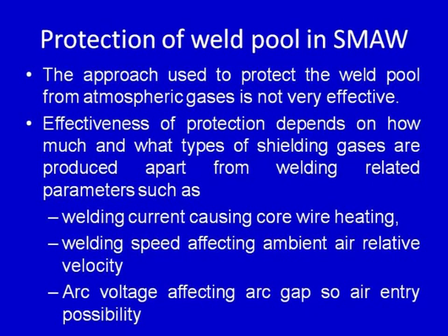So, the effectiveness of the protection in this process depends on how much inactive gas is produced due to the thermal decomposition of the coating material, and what type of shielding gases are produced, apart from the various welding related parameters.